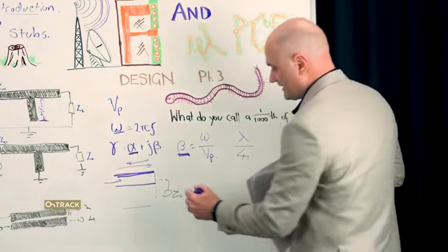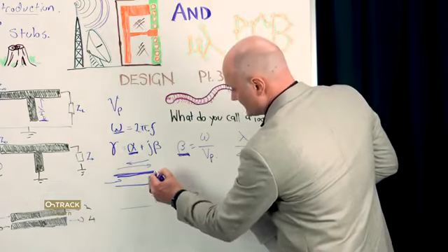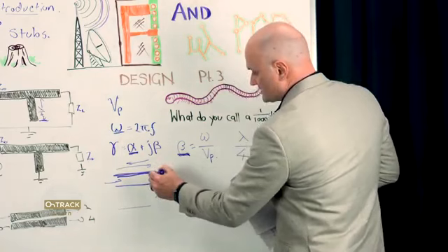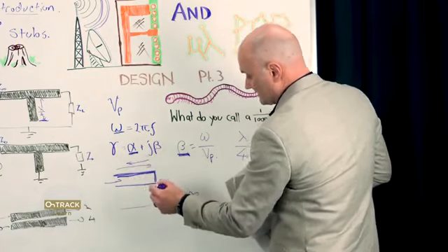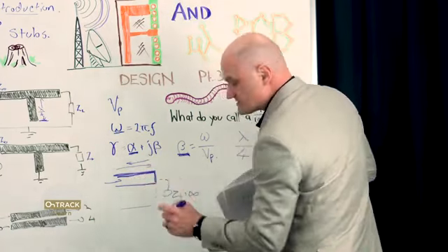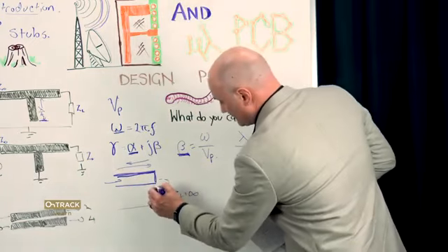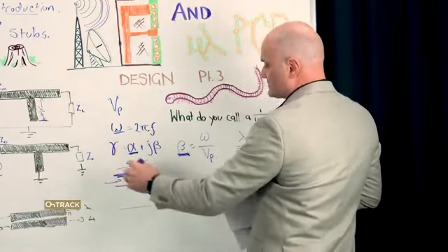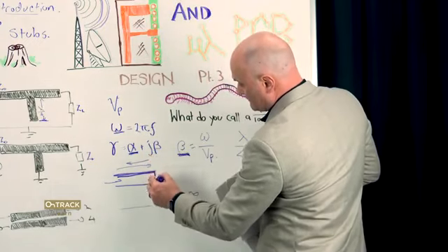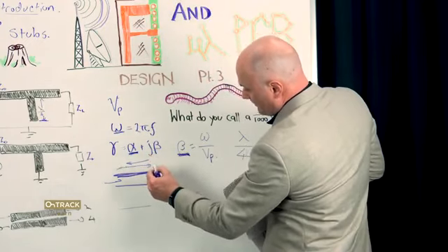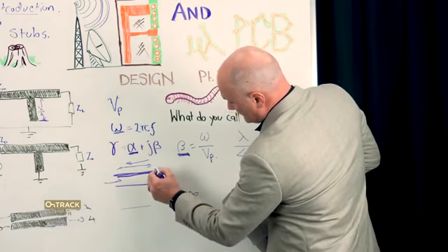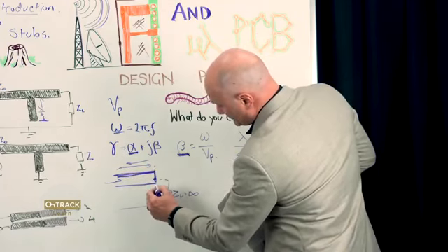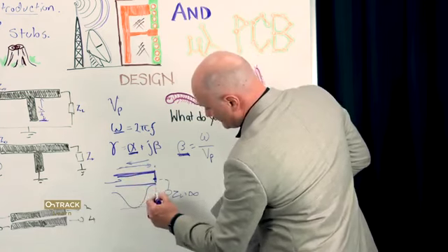That's fine. Because this is an open circuit, the voltage at this end can be anything, but the current must be zero. So the current is held at zero here, and the reflected voltage, when a wave reaches here, is effectively doubled.